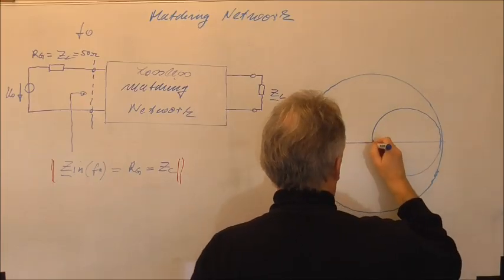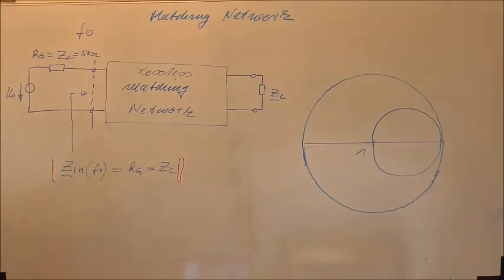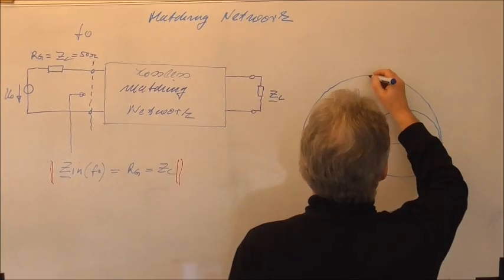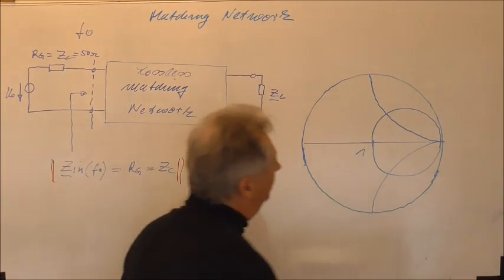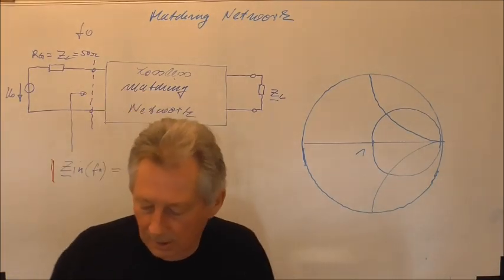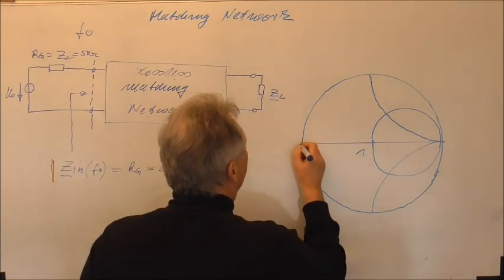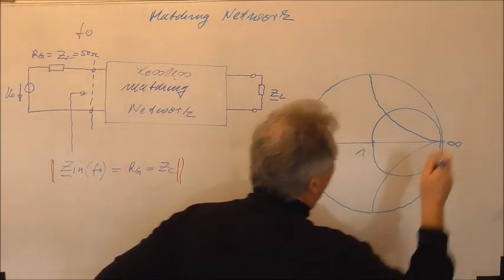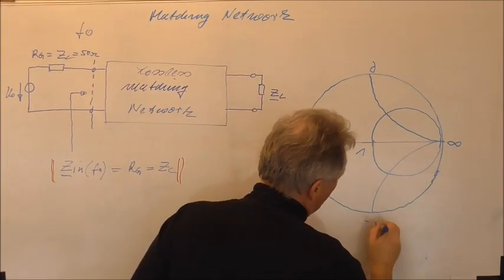You will see that this one circle is very important. Here in the center of the Smith chart we have a 1, and here we have the imaginary part circle of 1 and the imaginary part circle of -1. So this is now our Smith chart. Here you have the 0, the short circuit point. Here we have infinity, here we have J, and here we have -J.